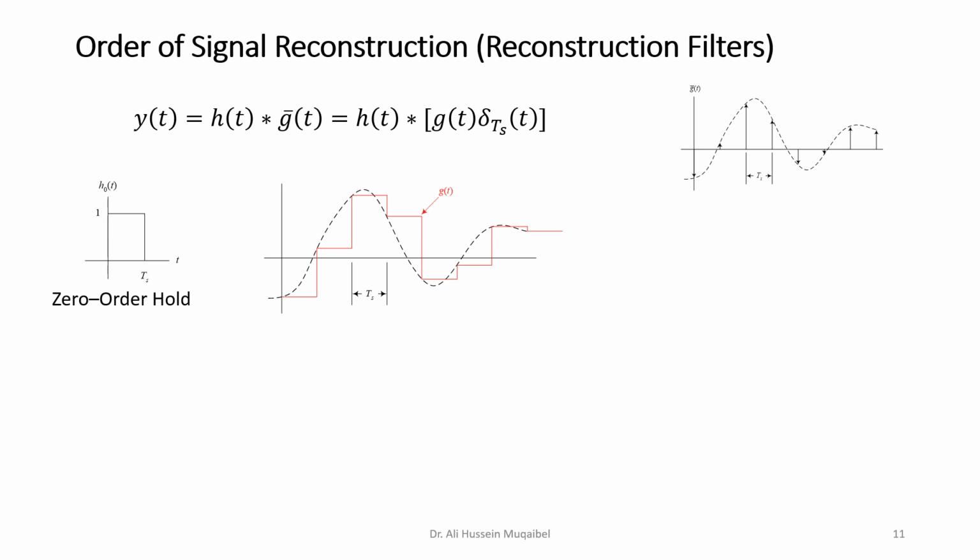Okay. What we have seen was the perfect reconstruction. Some people could make things simpler. They could find the reconstructed signal by convolving the sampled signal with a simpler transfer function, not sinc. They could use just a constant value, and this is called the zero-order hold, because you get the value and you hold it. You get the sample and you hold.